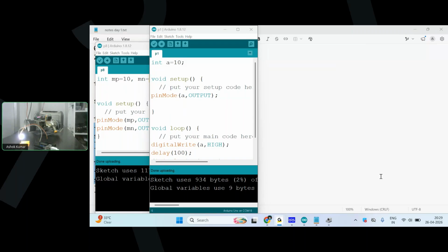It does not have a sufficient amount of current to sustain. So in that case, when you connect the motor of 1 ampere with the IC directly, the motor consumes all the current and your IC goes off. And if your IC goes off, automatically your motor is off. Once your motor is off, the IC again gets the current. When the IC again has the current, the motor again consumes the whole amount of the current. Again, the IC goes off, the motor goes off. And this operation repeats n number of times,